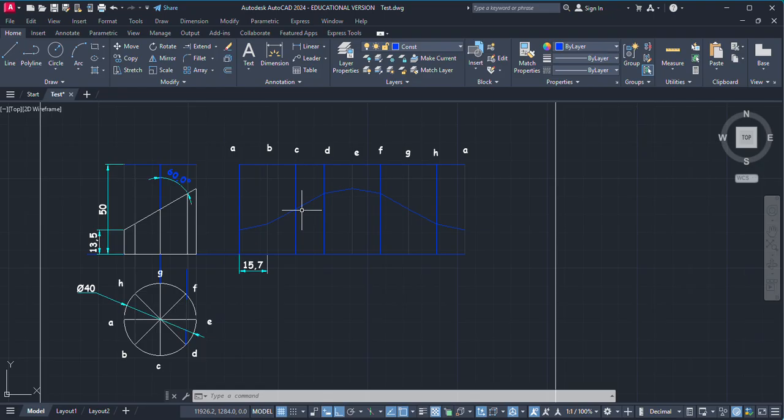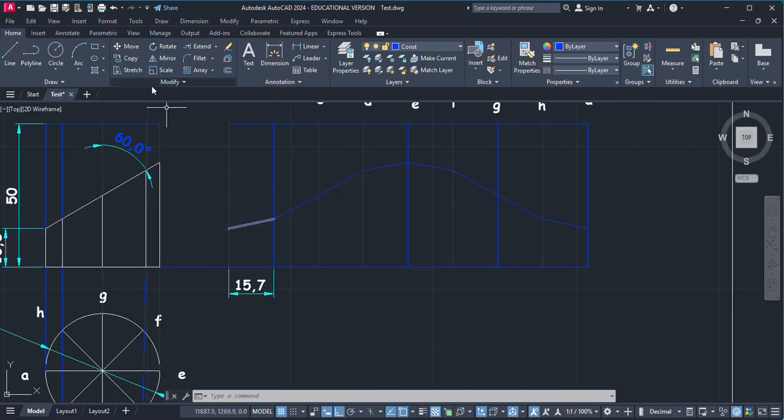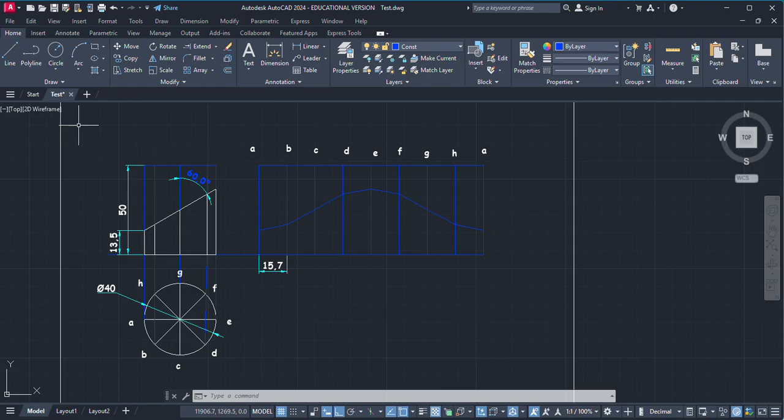To draw the curve in manual drawing, you can draw it through multiple points. But here, instead of creating an arc with the arc command, on the left side of the draw panel you will find a command called spline fit. Use this command to create a single curvature.